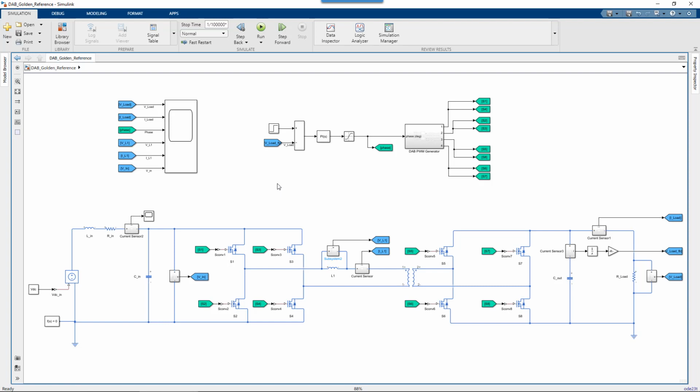If I have to do 1 or 2 simulations, it's not worth the time to try and make it run faster, at least in this case. Just run it as is. But let's say you're going to do a Monte Carlo analysis, you're going to do sensitivity analysis, something where you're going to be scripting this or using another tool, and it's going to get run hundreds or thousands of times. Or even if you're just manually tuning control loops and you just want to save a couple seconds per sim, you may want to see if there's a way to speed up your model. What can you do?